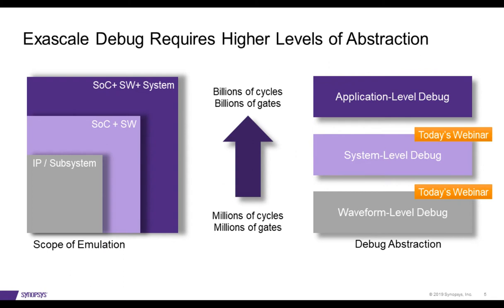Then there is another higher level on top of that, where you are trying to do application level debug of the SoC in system context. So clearly our complexity is increasing from millions of cycles and millions of gate designs to billions of cycles being run on billions of gate designs. In today's webinar, the focus is going to be on system level debug and waveform level debug, and in a future webinar, we will talk about application level.